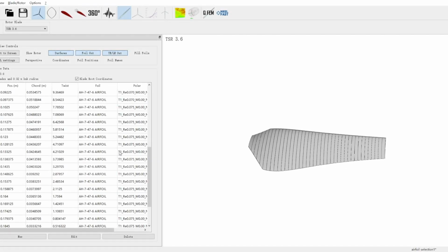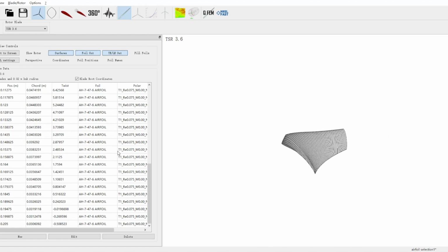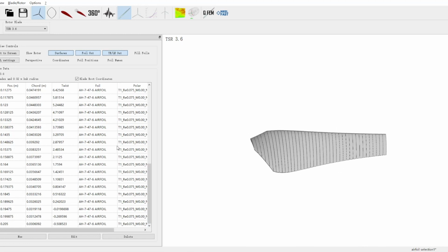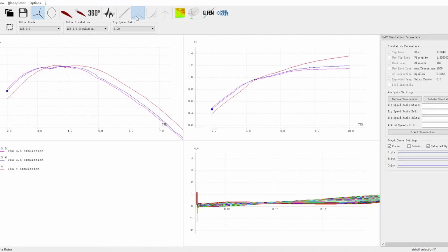Q-blade modeling. Q-blade has a built-in function of optimizing the chord length and twist angle of each section of the blade for some specific tip speed ratio. The results calculated by Q-blade were then used to verify the calculations done by our code. In the final design, the dimensions of the blade, optimized by Q-blade, were used. Modeling by Q-blade is an iterative process. The maximum power coefficients of the blades, which are optimized for a range of tip-speed ratios, are compared, and among all of them, at a tip-speed ratio of 3.7, the power coefficient is the highest.